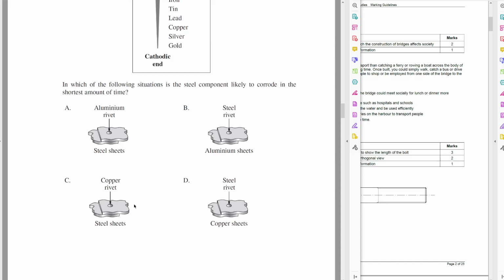Part of the other reason why I think about this is that we know that aluminium is a more passive material, the same as stainless steel. It has a passive oxide layer, and corrosion is usually not as big an issue because of that. It's not going to have a runaway corrosion problem like steel does. When steel rusts, it creates a feedback loop where the rust is going to continue.